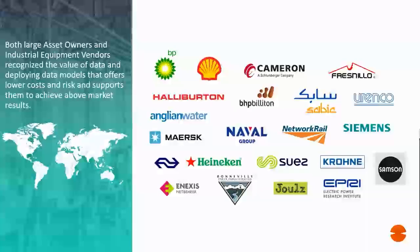That is sufficient to run a condition-based or predictive maintenance program on. However, especially when it comes to mechanically rotating elements, for example in power generation on steam turbines, it's sometimes necessary to have access to high frequency data, high frequency vibration data, for example. So it really depends. The need for high frequency data really depends on the type of failure mode that you're interested in to classify in your data.